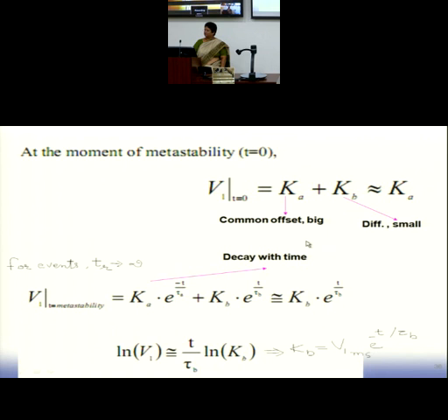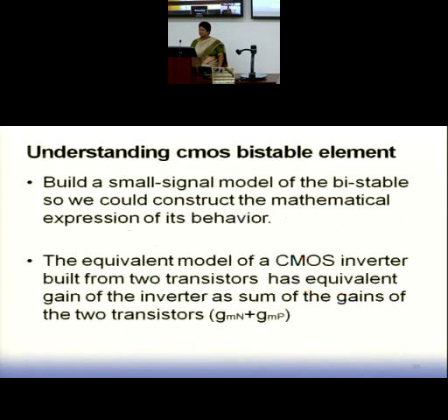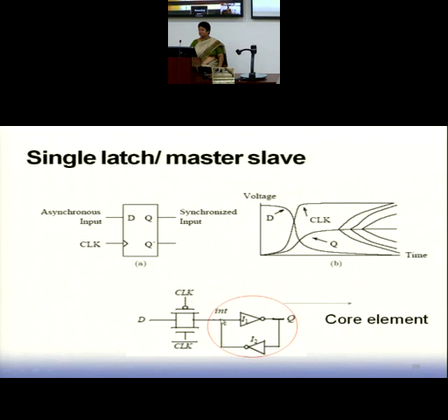Clear? Now this is very, very important. Why am I looking at the second one and not the first one? Because I am interested in finding the behavior at T very large. Metastability is happening only at T very large. Unboundedness is coming into the picture only at T very large. It is not getting stabilized. It is taking an infinite amount of time. In the beginning, it is only the input value that you would be getting at this internal node.